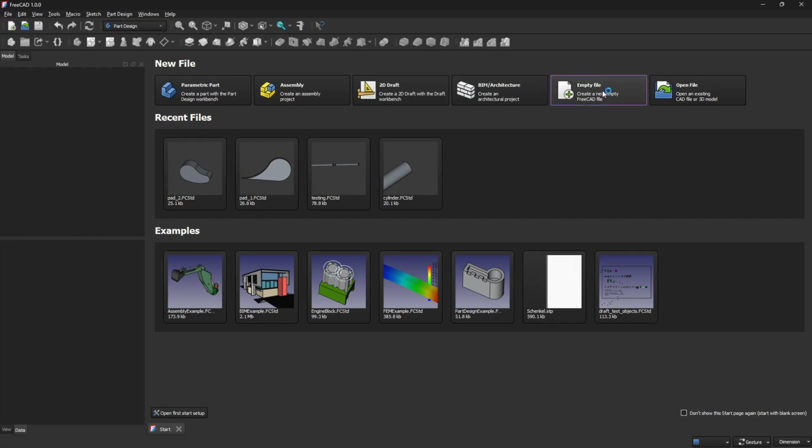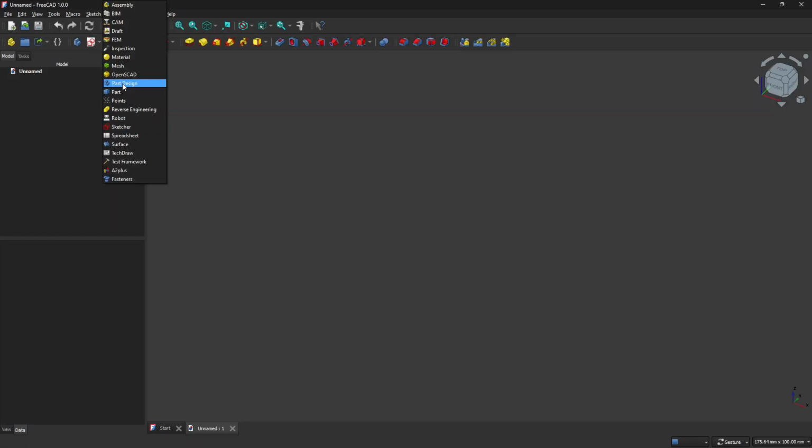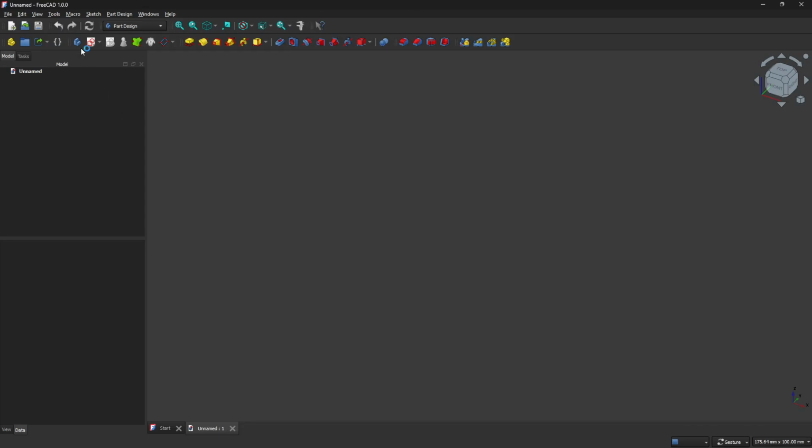To access the part design tools, first open FreeCAD and switch to the Part Design Workbench. Every 3D model in part design starts with a sketch. Here's how to create one. Create a new body. Click the Create New Body button to start working on a solid model.